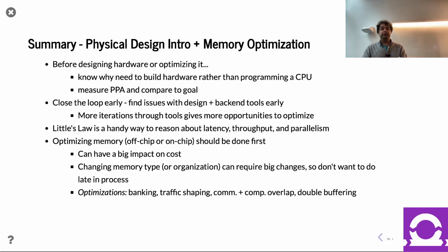As I mentioned earlier, I'm lobbing this project idea out there of, gee, wouldn't it be cool if someone had a Chisel generator where you could say, hey, I want a memory. From a user point of view, that's pretty simple. But under the hood, it knows what your implementation technology is and perhaps does the banking or appropriate double buffering for you, such that if you ask for 9 ports, it goes, oh, wait, you asked for 9 ports, I'm going to do 2 ports at a time, and I'm going to replicate and bank for you internally. That could become a fun project.